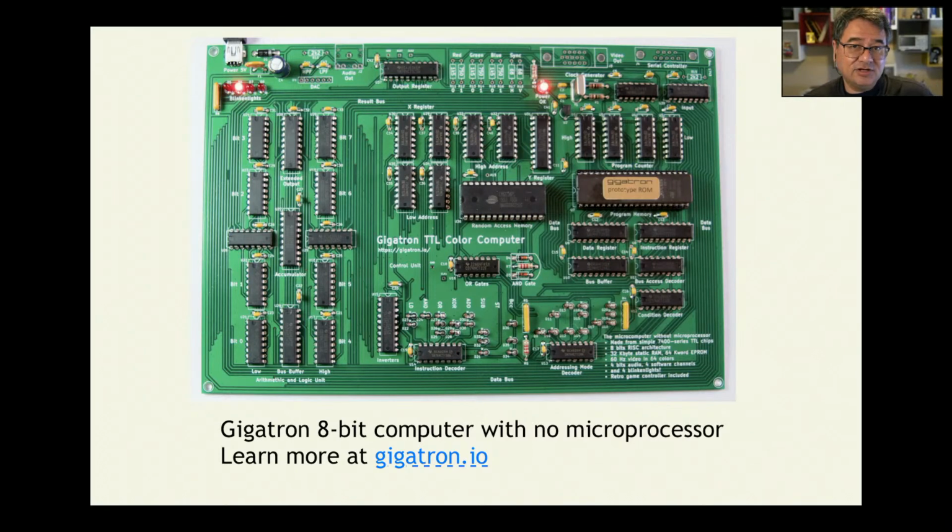And there's only 8 instructions in this processor. You can actually see them listed right here. And so what happens is the instruction comes in from memory. 3 of those bits go through this decoder, and depending upon what that bit pattern is, one of those 8 pins goes high, and it says, "Oh, that's what this thing is. This is an add instruction." And then if it's an add instruction, the data comes over here to the adder, where 2 values are added together, and then the data gets stored back in memory.